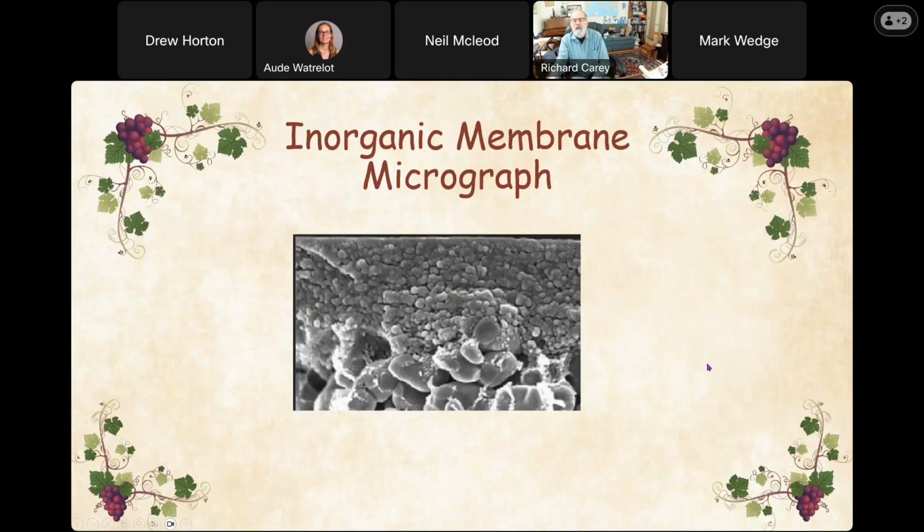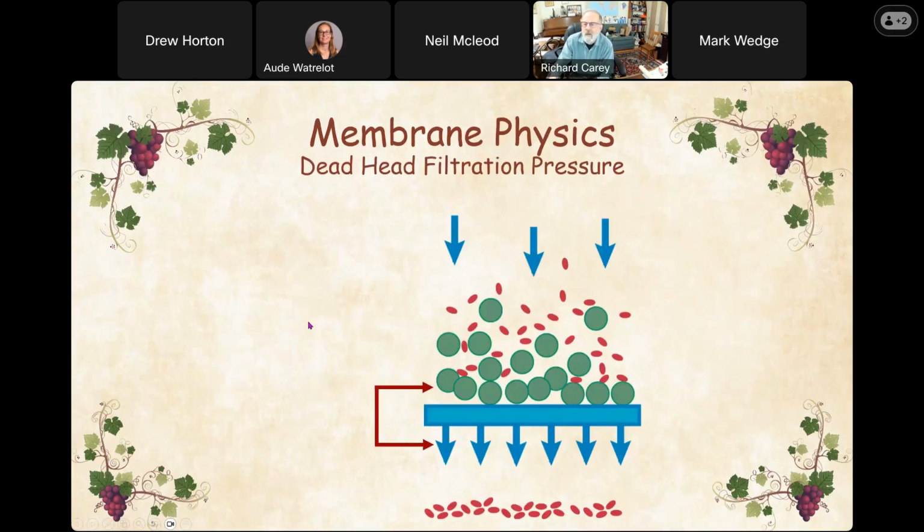Then there are inorganic membranes, made with aluminum oxides. You can get different size aluminum oxides for the coarse area, so you have that same asymmetry, and then a different kind of aluminum oxide to give you a little bit more structural strength, and the actual material that gives you the surface is silica. Many times these are called ceramic membranes because you have to take the material and heat it in an oven to get it sintered together to hold its structure.